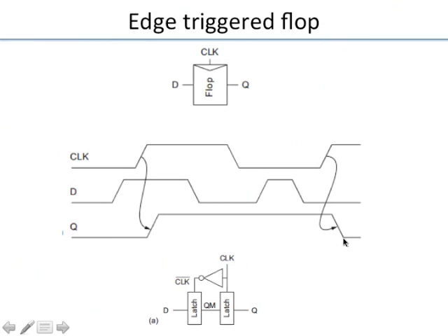So latch is there and flip-flop is there. We have to distinguish the two. Sometimes in a loose way people use one or the other, and it can become very confusing, because a latch has a transparent phase and an opaque phase. A flip-flop is like a camera. It is edge triggered, either positive edge or negative edge.